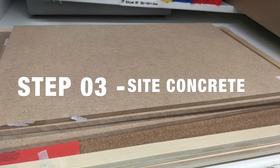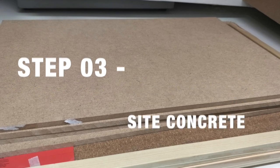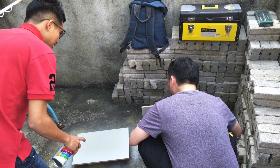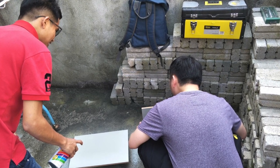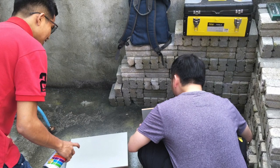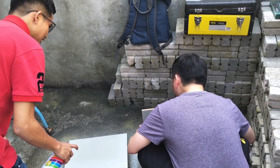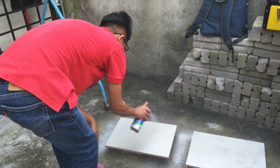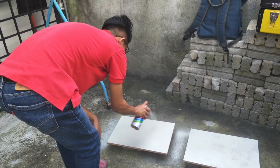Site concrete is a material poured to create a solid level surface. The site concrete must be at least 100 millimeters in thickness, composed of cement, fine aggregate, coarse aggregate in the ratio of 1:6 to provide minimum strength. On the working model, we are using 2 density fiber boards and spray in grey color.